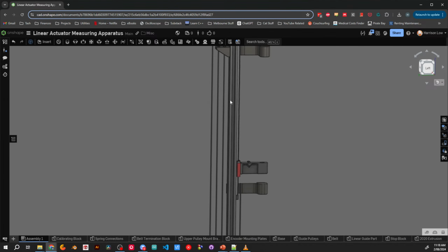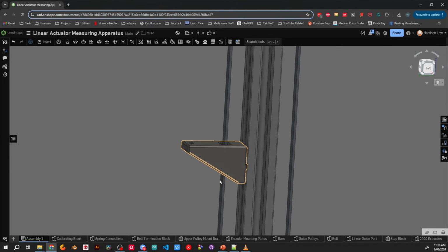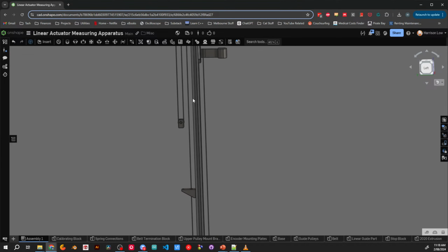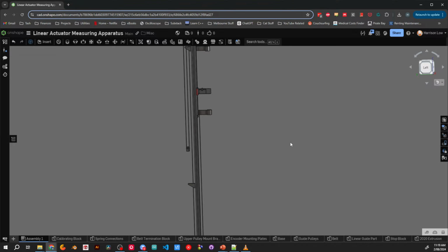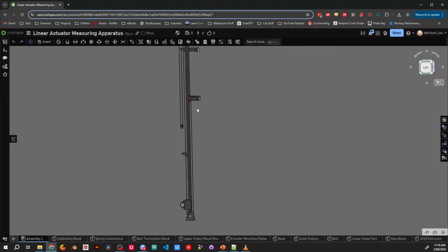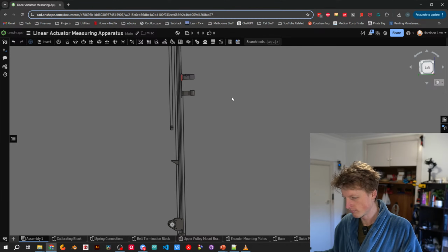Yeah, and the reason why I've got this pulley system is so that the spring, which is attached to this block and this block here, doesn't need to have the entire stroke that this has, so the spring will only need to stretch half as much as this part moves, just because I didn't want to overstretch my spring. And I was intending rather to use this in a way that would have the slider moving the entire length of the full aluminium extrusion. I'm not going to end up doing that, so this is a little bit overkill for what I've actually done, but whatever.